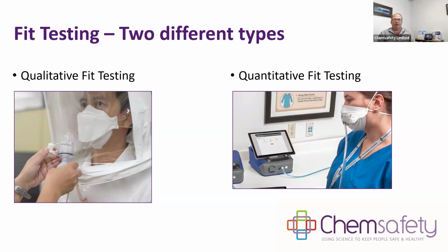of respirator. It is a lot cheaper of a setup, but also the results can be faked. If someone's a pretty decent actor or has good control and composure, they can pretend they're not tasting it. And obviously we have no way to verify if they're tasting it or not. Now these Bitrex and the saccharin sweet solution, they do, to me, taste horrible. So it's quite hard for people to fake it, but apparently it has been done in the past.